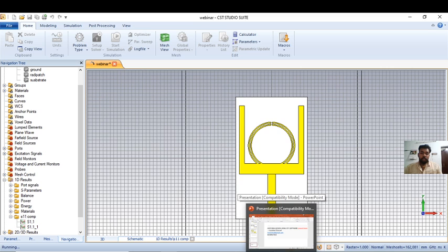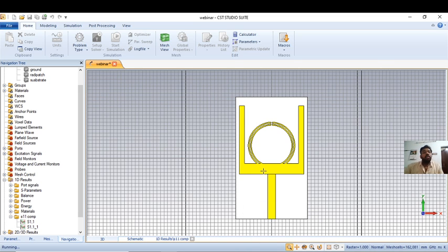And next one is when you are going to make use of a metamaterial. You have to place that metamaterial at the place where your surface current is maximum, right? So first you have to design your antenna and analyze your surface current. After analyzing your surface current, you can find out the maximum surface current area in your region.